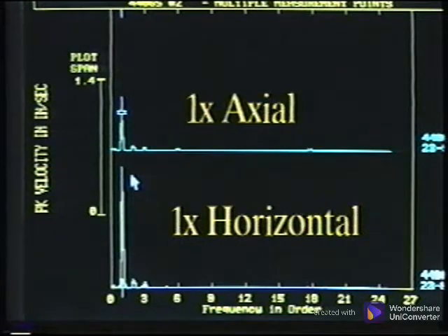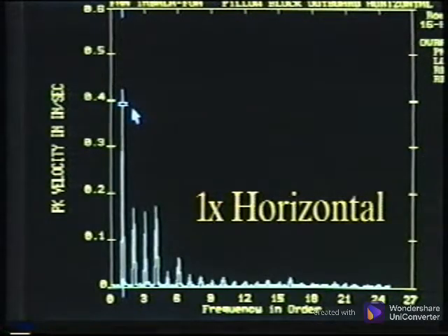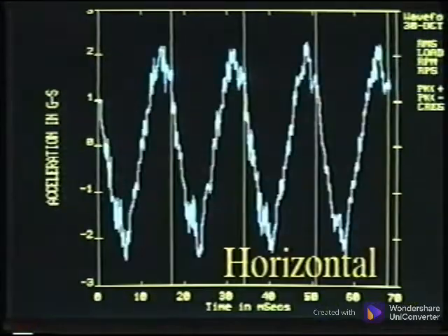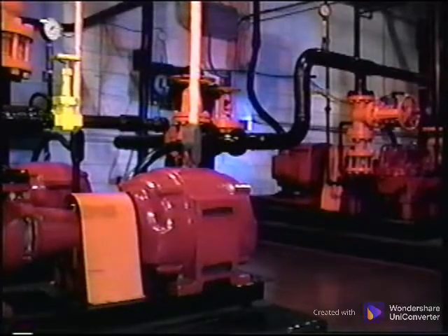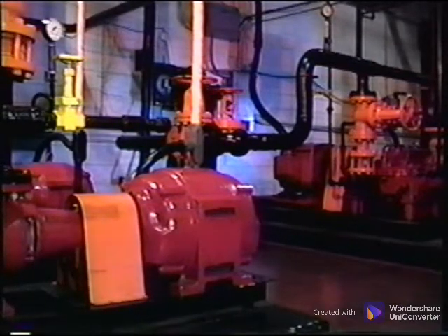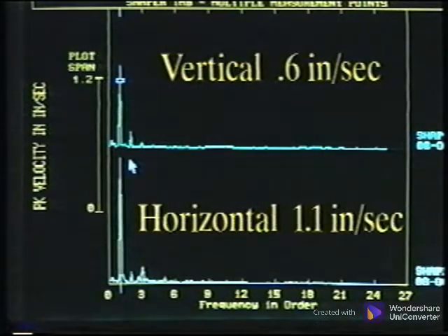The radial measurements may have other peaks present, but the turning speed peak must be dominant before balancing will substantially affect the machine's condition. The waveform data will have a dominant sine wave, and even if it is very busy with other energy present, there should be an underlying sinusoidal shape. Depending on the mounting, the machine may have more freedom to move horizontally than vertically, or just the opposite. But if one radial measurement is more than 3 times the other one, suspect another problem such as resonance and perform tests to check the phase.